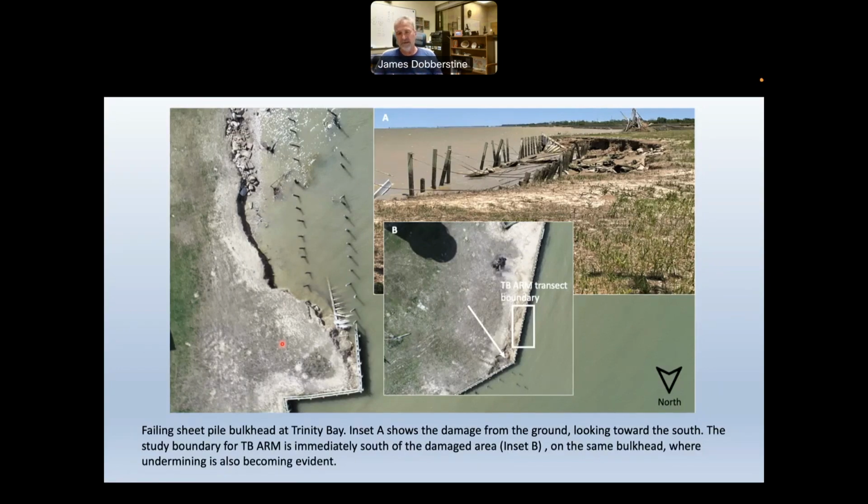It actually does. But most residential bulkheads are not anywhere near as well engineered as their industrial counterparts that you'll see along ship channels and where you have barges and major ships docking. These things are relatively simple, low cost, and not particularly durable approaches to shoreline stability management.